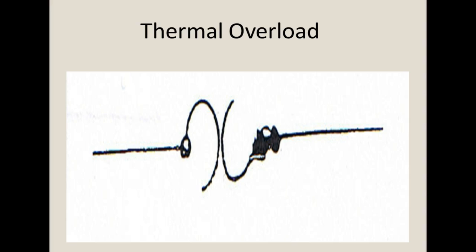one throw to close them. Some kind of armature bridge in there. Now I got 2 circuits on, so that's double pole. If I had 3, triple pole, right? I got a single pole, single throw there. It says a single throw. Single throw, that's right. The other one is a double throw.